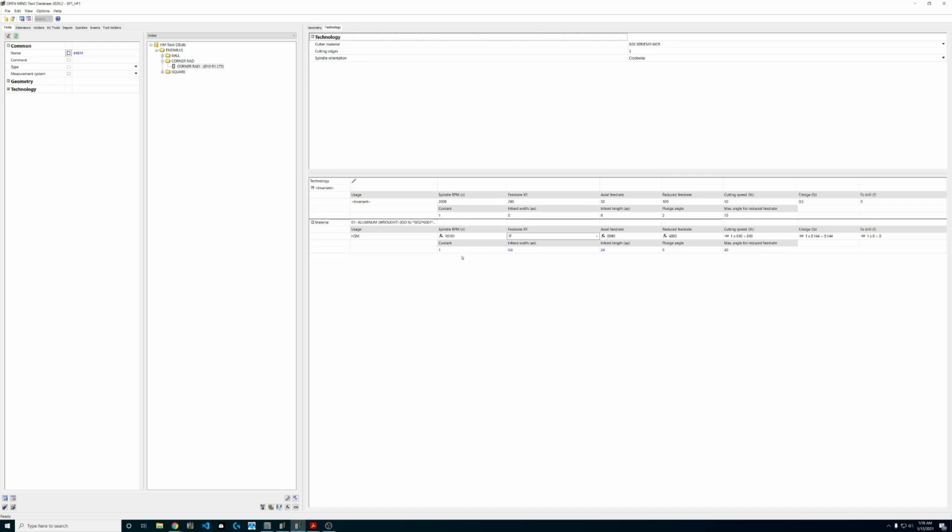Alternatively, we could actually disconnect or unlink this data and use the data direct from SGS as provided. But there's a reason we want to keep this link and actually modify the multiplier. When we're running these tools, we might find out that there's some more headroom in there. And instead of going in and changing 50 million usages, because we've finally built up our tool database to include 200 tools and each tool's got 10 usages, we can just go back to where our materials are defined, select this cutter material and just bump up the feed rate a little bit. And that's going to modify the data for all of our tools that use that value.